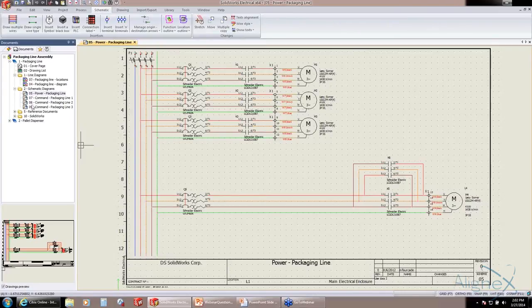So on the left side of my screen here, you'll see the project breakdown with some of the different documents that are included outside of just the regular detailed schematics. With that, we'll start on our detailed schematic, and what we're going to start off with is building a motor circuit identical to this current circuit that is set up for motor 3 here.